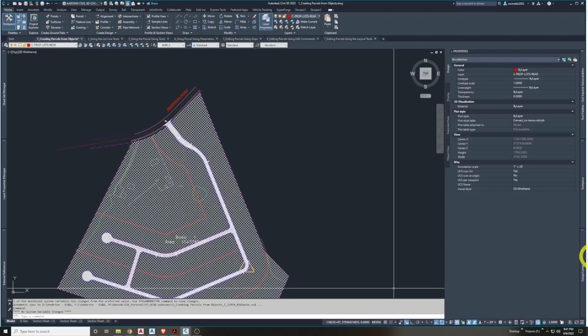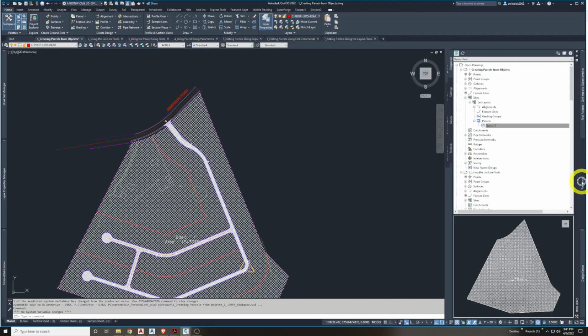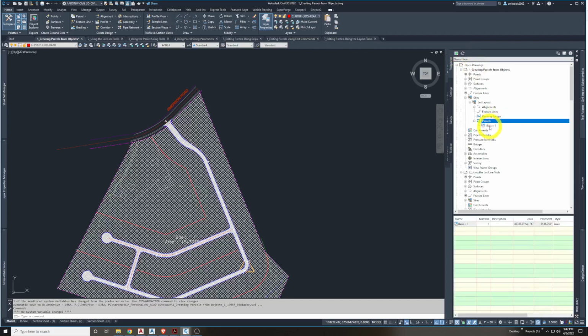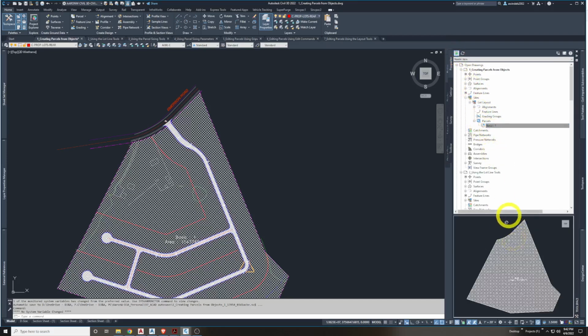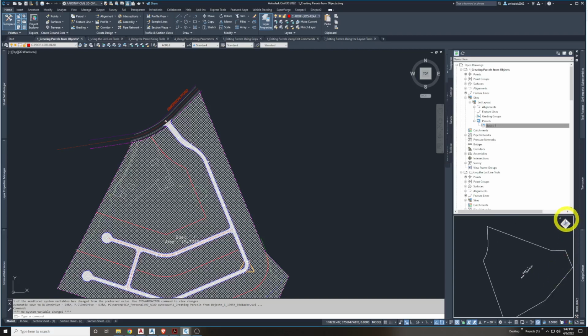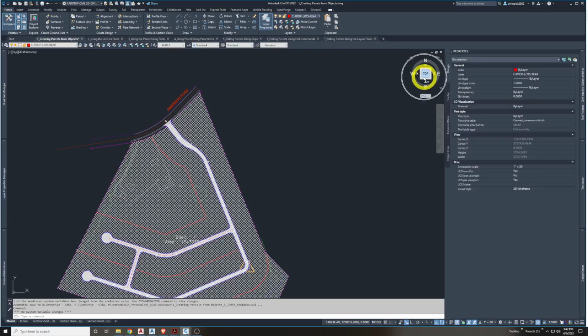You can see it here physically, but if I hover on tool space again, remember you turn tool space on here in the home tab if you need to, but if we turn that off and I select here, it just shows a blank screen. So I'll toggle this back on. That's all it's saying, it gives you a little extra preview. You can even do some rotation here. It's almost like an extra object viewer. I'll put it back to top. You can rotate it around just like you can here in the wheel in your model space.